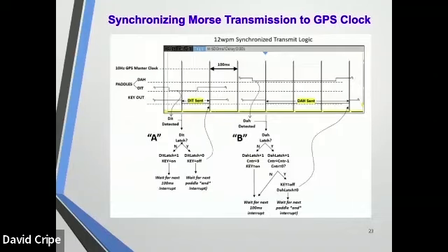It's kind of a complex diagram, and it's been updated since, but nonetheless, this just takes the random closure. These are the 100 millisecond time boundaries, if you will, and this is a random closure of either a dit or a da. The software catches that edge and saves it with a dit latch or a da latch in order to remember it so that I can flip the output in synchronism.